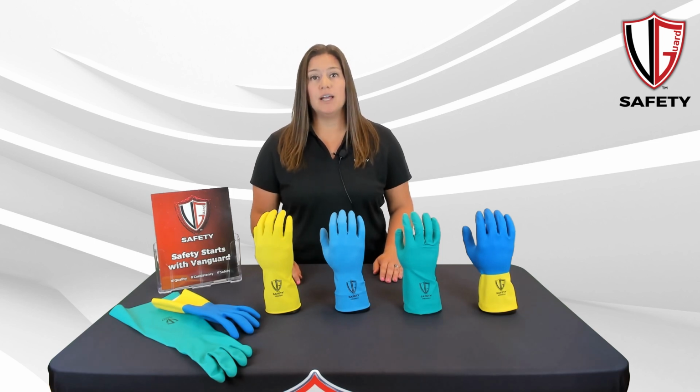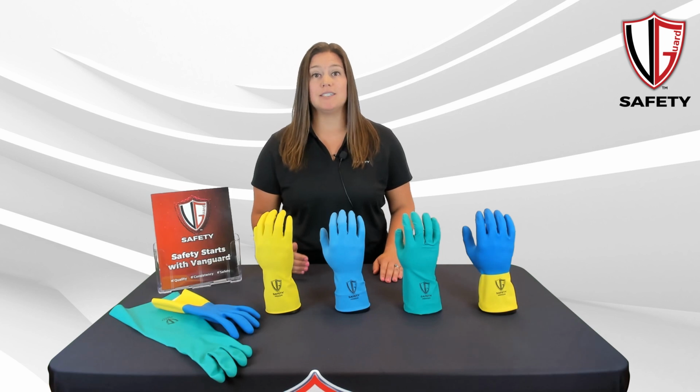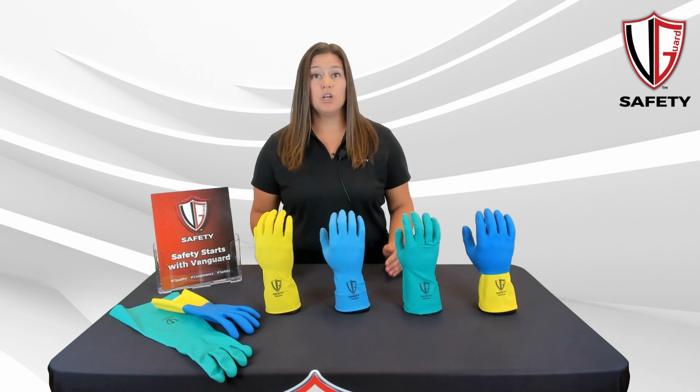This is done by utilizing 3 samples from the palm of the glove and testing each one against each specific chemical. Gloves with longer cuffs, such as 18-inch in length and more, results in 3 more samples taken from the cuff area as well for testing. The breakthrough times are measured and the lowest result is used.